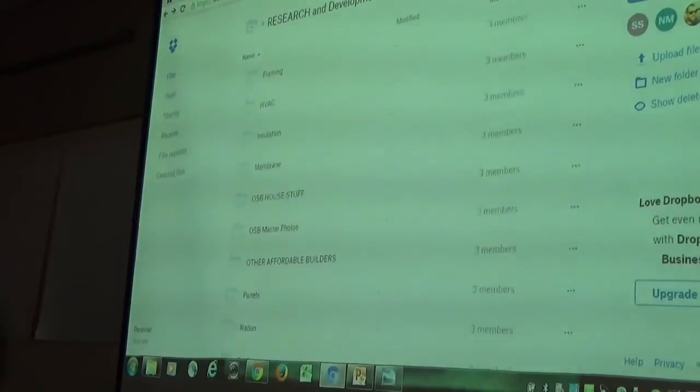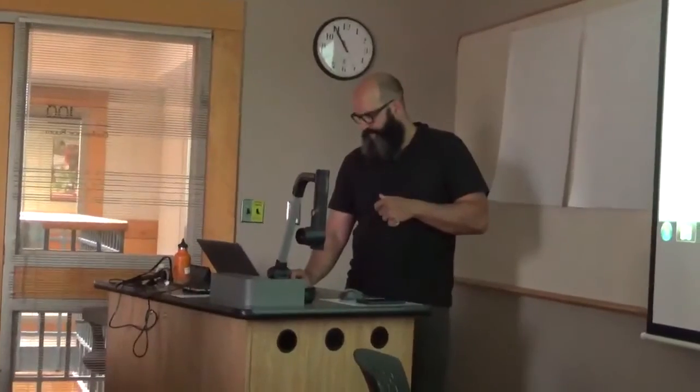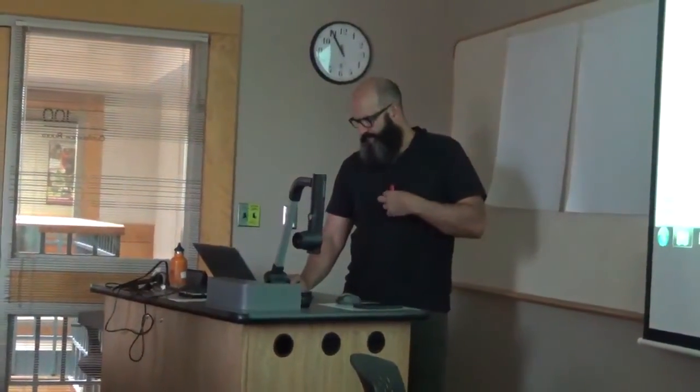And so we can fit 3-ply headers, we can fit a lot of the framing that we get accustomed to doing, double trimmers and single kings and all of these things, that this is the way I've been doing it with 2x6 walls for at least 10 years, and if I switch back to 2x4, that's an interruption to my system.